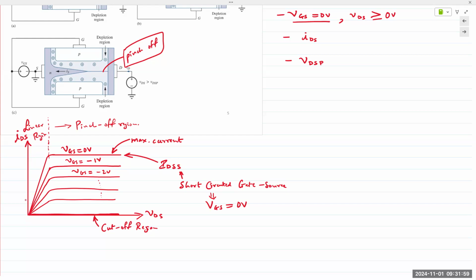We are still controlling the current flow via the gate, but we have to apply a negative voltage to actually reduce it all the way to 0. Does that make sense now? And when we say the device is normally on, we are referring to the fact that the channel is open. When you buy a JFET from the manufacturer, it's always on.